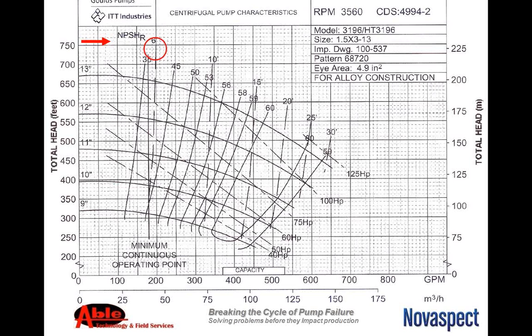Okay, so this is the net positive suction head required that we had just talked about. 6, 10, 16, 20, right down the line. What I want to bring about here is that's what's required, but if you look, as the flow increases, so does the NPSHR. So we start off with 6 feet at a very low flow on the pump of 200 gallons per minute. But at the best efficiency point, this 60 here, in the center, it's asking for about 20 feet.